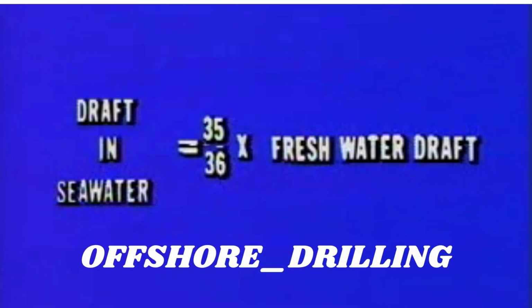When a vessel goes from salt water to fresh, or vice versa, the draft is always less in seawater. The formula to remember is draft in salt water equals 35 over 36 times draft in fresh water.